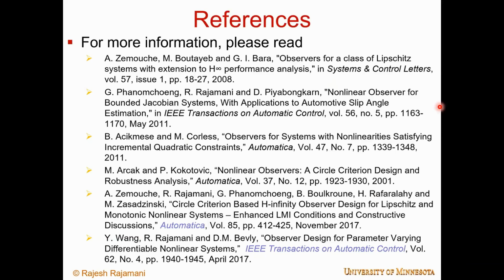So that is one of the advantages of these LMI type of solutions for nonlinear observer design, especially if you compare it to EKF or the UKF. You don't need to keep solving for the observer gain. You essentially try to get one constant observer gain, and that observer gain can give you global stability. So the EKF, for example, would give you local stability, and you would keep solving for the observer gain. But here, you would get global stability with constant observer gain.